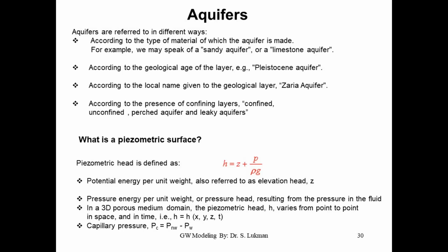And when we say adversely affected, in this case, more often than not, we are talking about the piezometric head. Because it will be adversely affected if the piezometric head goes down. It means you are depleting the aquifer in no time, isn't it? But if it stays relatively stable, the depression is manageable, and then you can go ahead with that pumping rate. Otherwise, you may have to review the pumping rate so as not to affect the aquifer adversely.